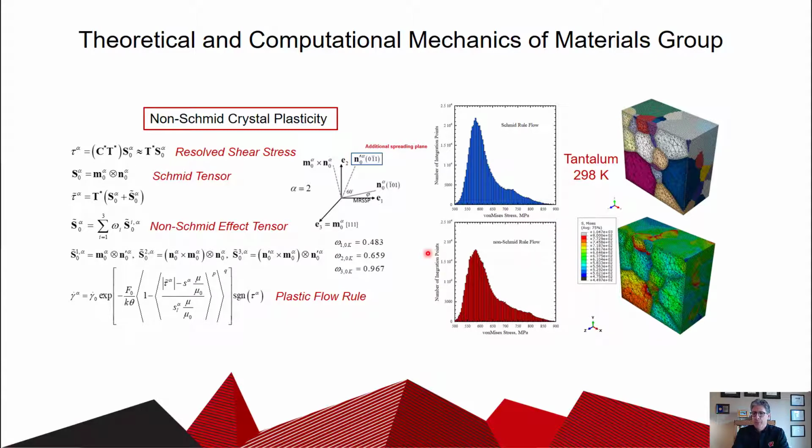So I also do micromechanical analysis and study of metallic materials. The images to the right are a numerical model of a polycrystalline metallic material of tantalum, which is an interesting material. That is a cross-section of a cube, and the length of that cube is 165 microns, and the average grain size of that material is 42 microns. Each of these different colors in this cross-sectional image of this cube is a different single crystal.